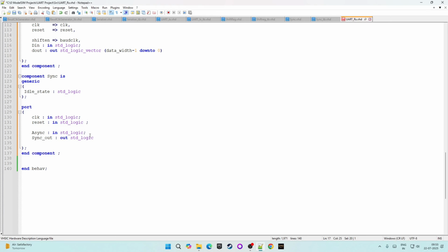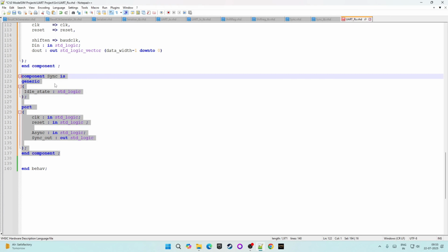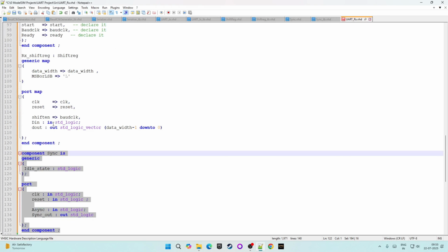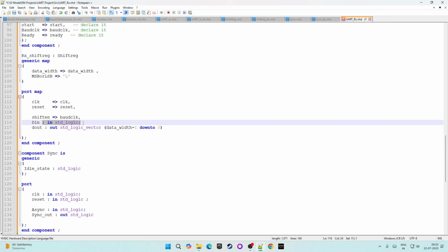And for this, we will going to use this synchronizer module, right? So suppose let's give it some name and we will assign that synchronized signal to this D input. Okay. So suppose let's say we have an internal signal that is named as RX synced. So this RX sync will be the synchronized version of our D in signal or D input, right?